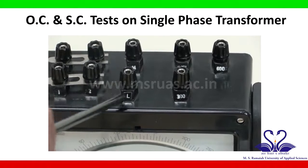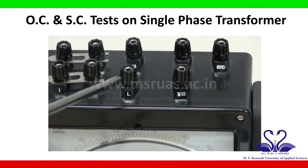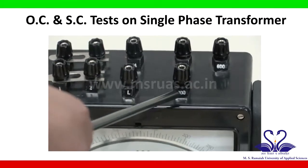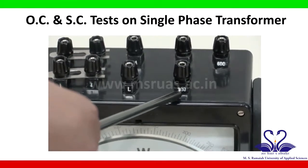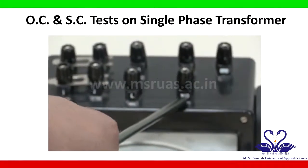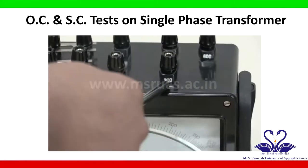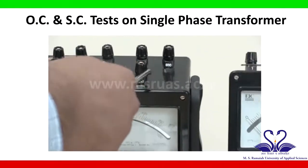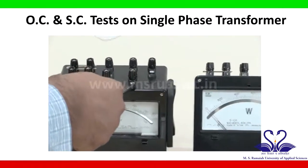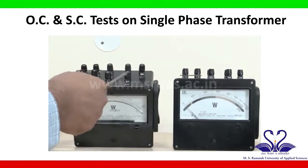L is line, which is always connected in series, which is called the current coil of the wattmeter. V, we can select the range like 300 and 600 volts. Potential coil is always connected in parallel to the circuit. 300 and 600 are the ranges that need to be selected for voltages. This connection will remain the same, any one can be chosen.